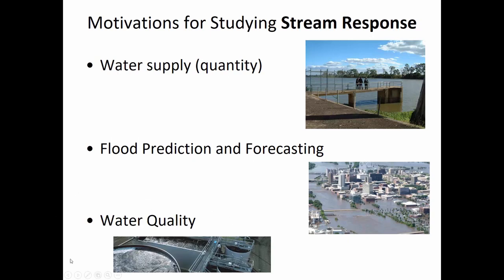It also has some implications having to do with water quality, and you've probably noticed if you've looked at the Ohio River that it changes colors as much as it changes height. And when it's been raining a lot, it kind of turns a brownish color. The reason for that is that, coincident with really high flows through streams, it's able to scour more. It's more turbulent, more sediment, and so there's a lot more scour of the soil particles,